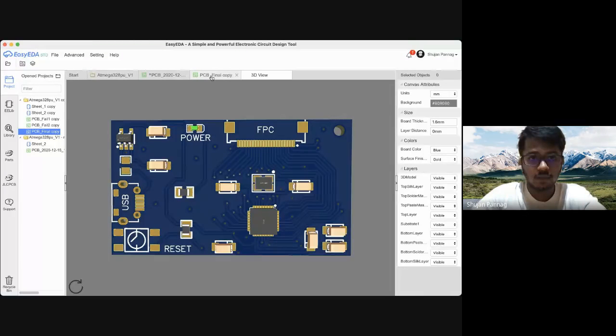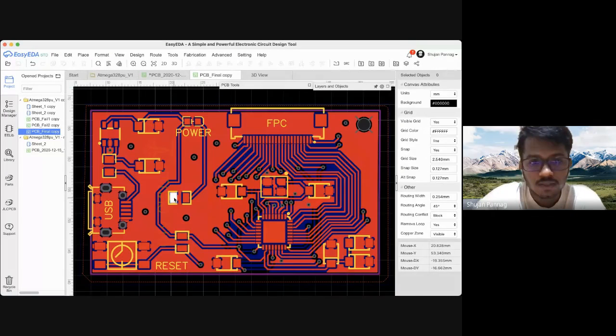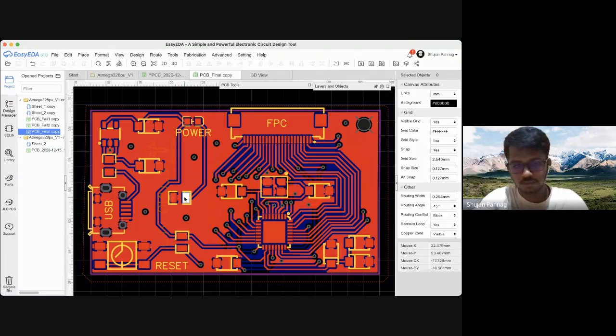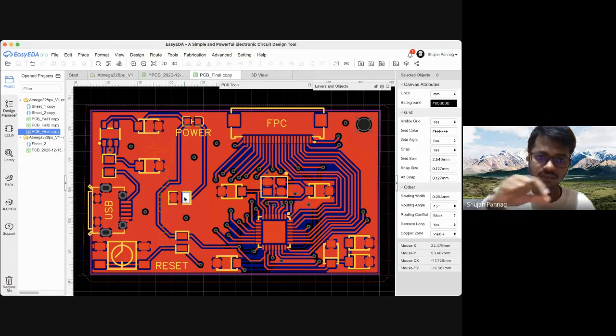And another trick, I would say, tips. I've used these capacitors, which are actually bigger than the pad length. That is actually not good, because what you're doing is not impedance matching. So always use any component which has an equal thickness to your copper pads or copper tracks. That way it's an easier impedance path for the current to flow through. The best choice would be, I've used a 3216 package, so that's 3.2.